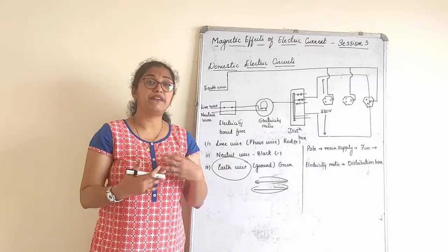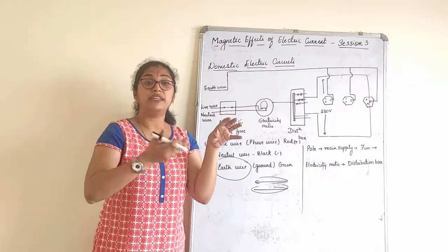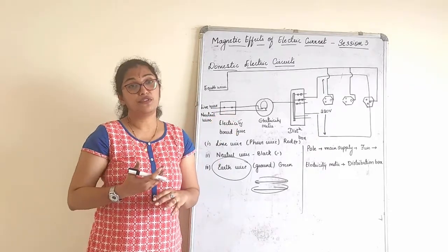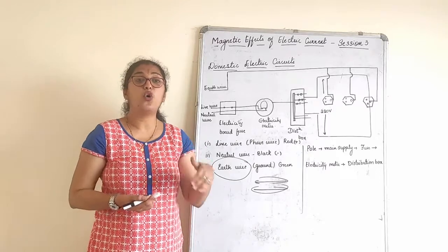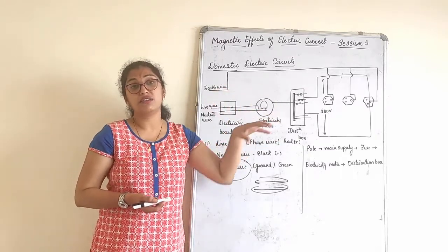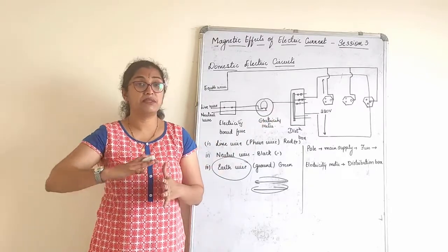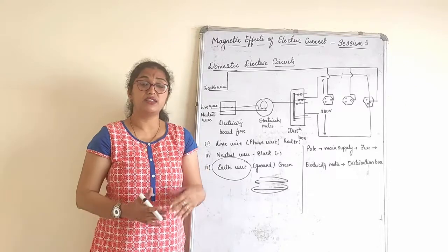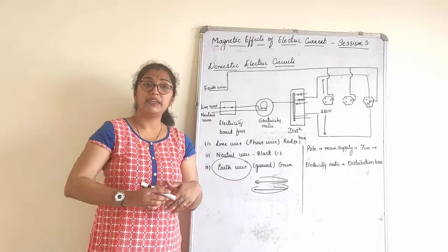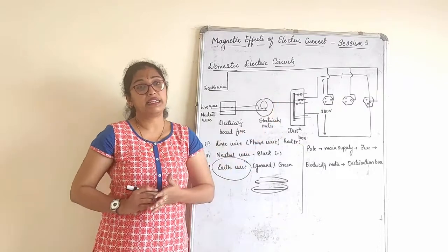Simultaneously, 4 to 5 appliances are running together on 5 amps, heavy appliances also. At that point, the name itself tells you: overloading. There is an overload of current on the circuit, and that might burst the appliances or anything can happen. That might also lead to short circuiting and other things.